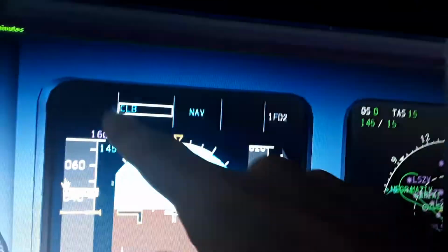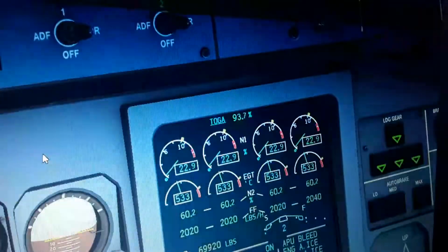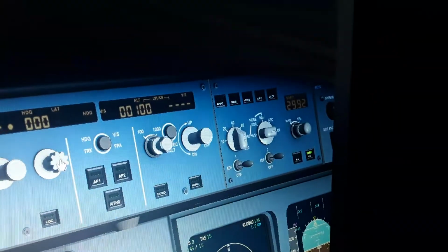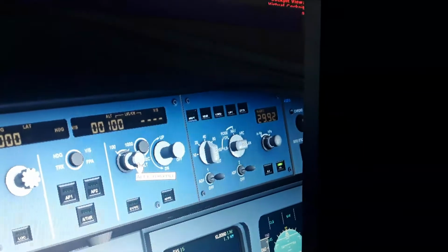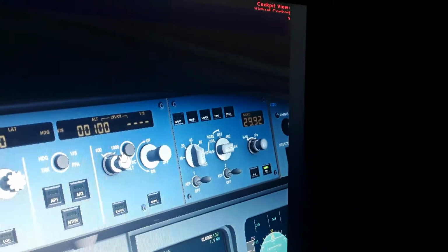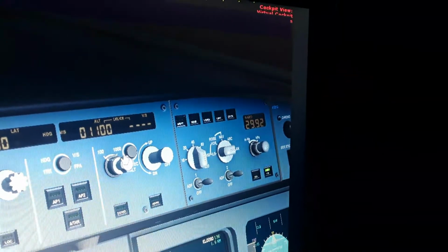So this is the primary flight display, the flight mode annunciator that I was telling you about. The heading of the flight control unit and autopilot, the flight director, the localizer. I'm gonna turn on the ILS. I'm gonna show you now. So we have 25 minutes to go for this flight, so I'm gonna make it very fast. So I'm gonna use more altitude here.